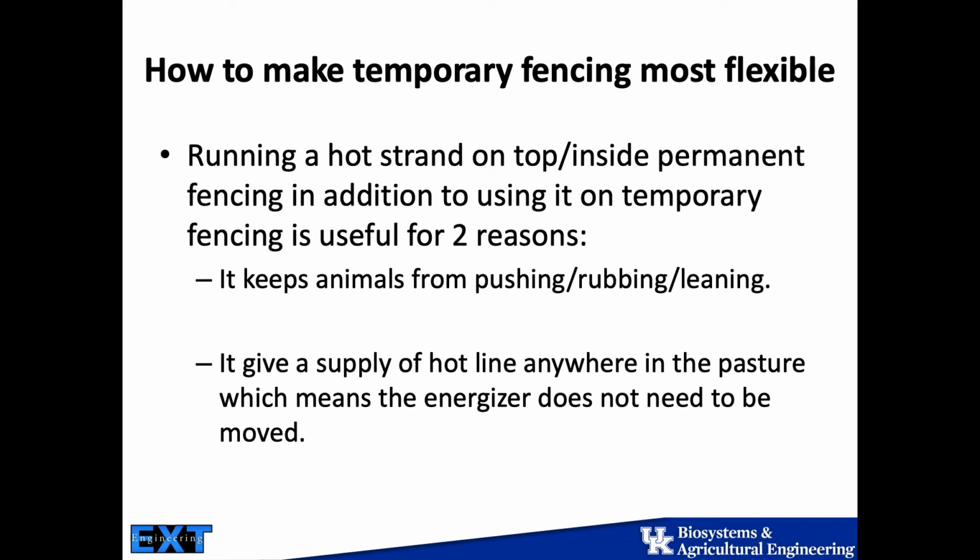Steel posts, long term, are not the right solution for a permanent, electrified fencing system, because they're painted, they tend to rust, and there tends to be some corrosion over time. But you have a lot of metal in the ground on those longer fence lines, and you probably are getting grounding from that. Among the things you want to consider, you are correct: if you had some sort of electrical storm, you could have some real challenges there. It could get very ugly.